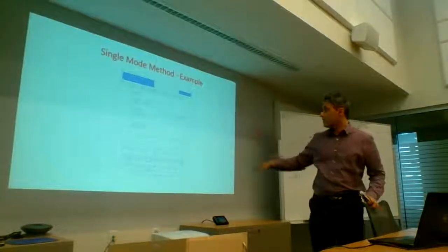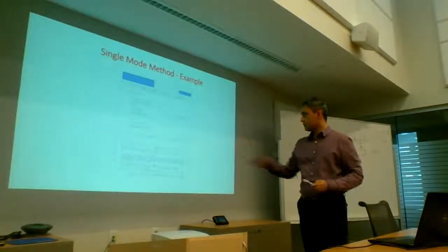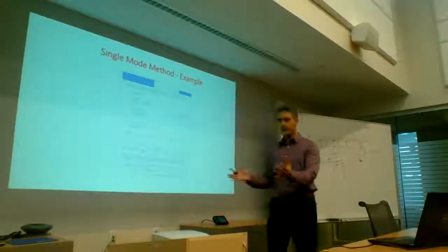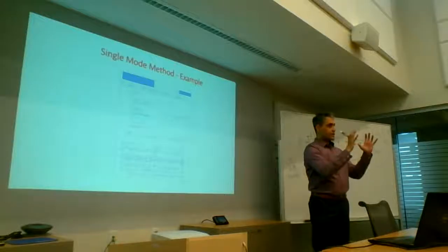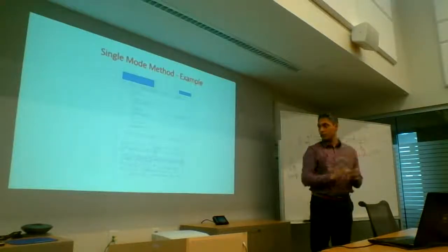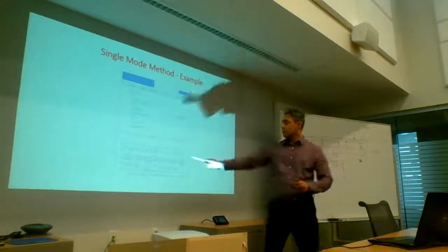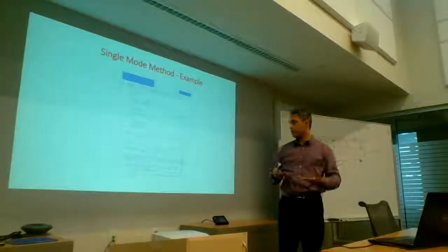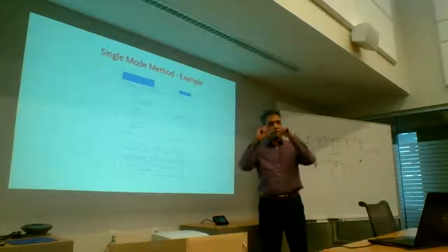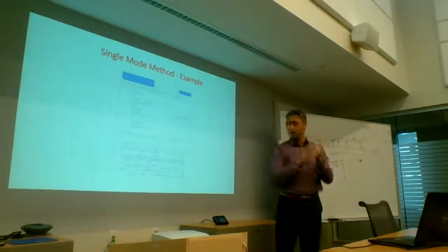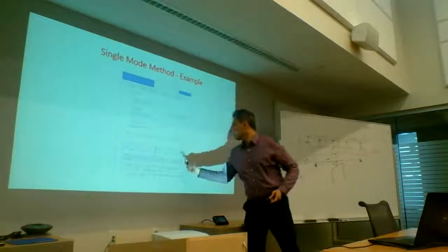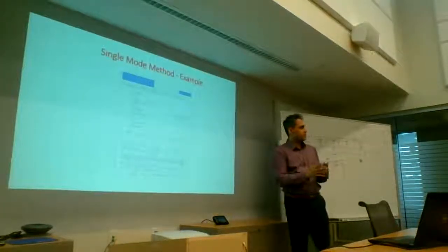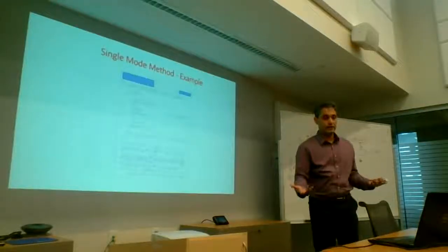Okay, so that's just giving you a lot of the information as to what the bridge looks like. This is the pier. There is a section 3, which is either side of the pier. At the pier locations, you tend to see a lot of negative bending moments, so the sections get heavier. Then in the mid-span, you see more positive moment. The sections are a little bit lighter, but now your bottom flanges are thick, the top flanges are thinner. And then section 1 sees minimal, so now you have another opportunity to skin up your sections because you don't want to use material where it's not required.